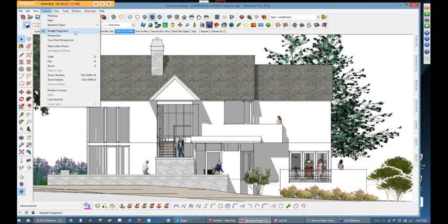And it needs to be in parallel projection. So without parallel projection being selected, and without one of the standard views being selected, you're never going to get a dead flat elevation. Do not try to do this manually. You're going to have a heck of a time. I did that once and exported to AutoCAD and proceeded to try to fix the drawing, and then realized I had made this error. When you don't do this, you get all jagged lines in AutoCAD and in Layout.